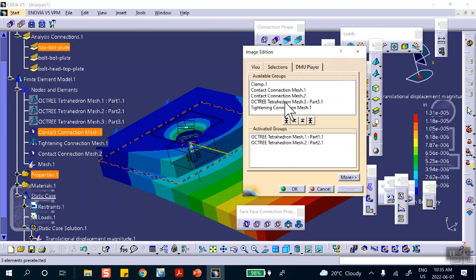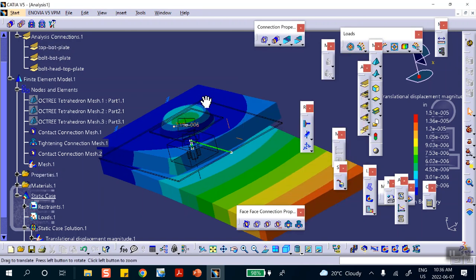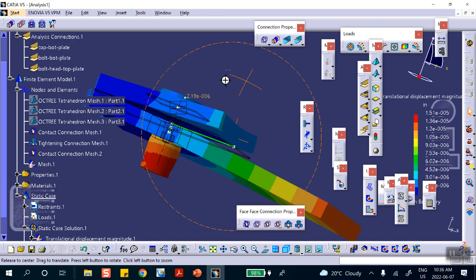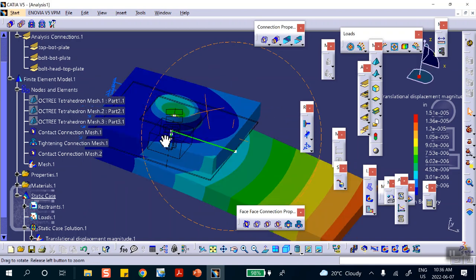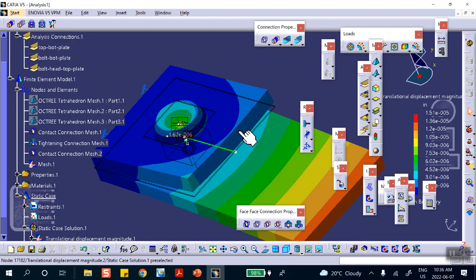This is the other mesh, which is the bottom one. And there is the bolt. Where's the bolt? Yeah, the bolt. We are not discussing accuracy here. First of all, notice what happened. The top of the bolt, which was a bolt head, which was flat, now it goes kind of down. That's because of the way the software is implementing the pretension. It's as if it sucks it in, but it can't penetrate because of that contact that they put in there.